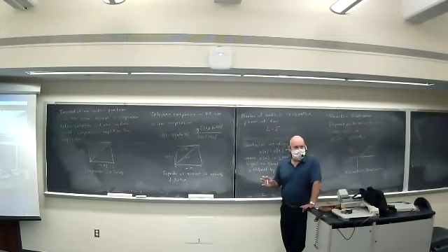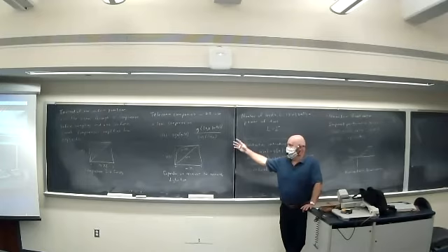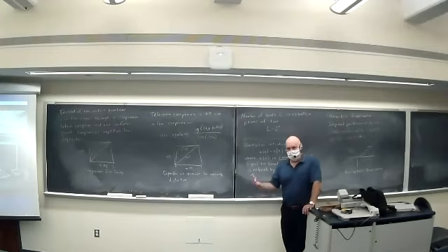Now we have a bunch of different telephone companies in the US, so they all have to use the same standard, and that's this curve. At the receiver, whatever regional telephone system your endpoint call makes it to, they have to do the expansion using the inverse curve. In the US they use this mu-law compression.